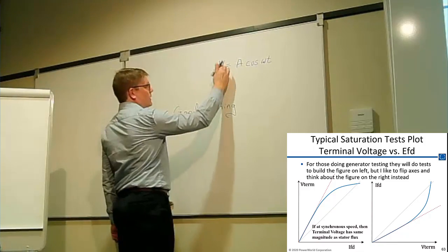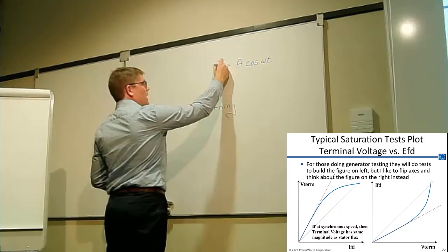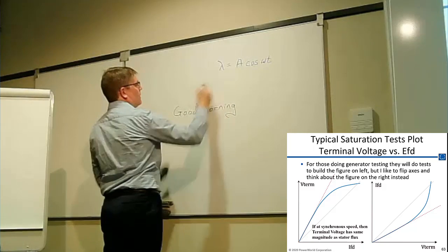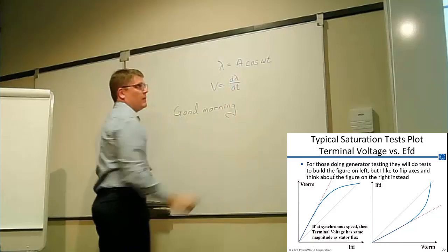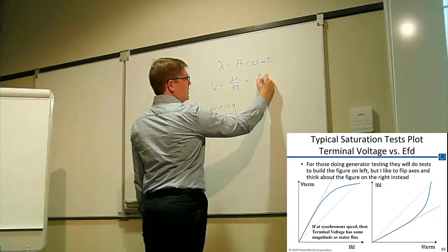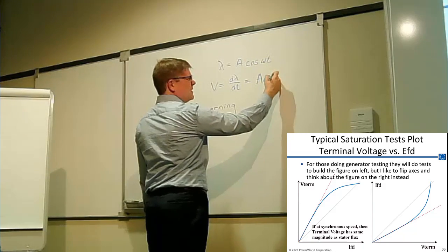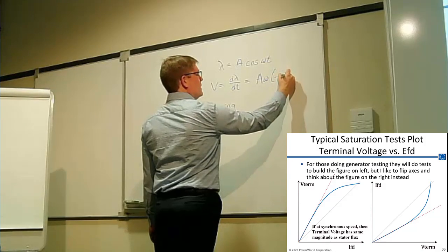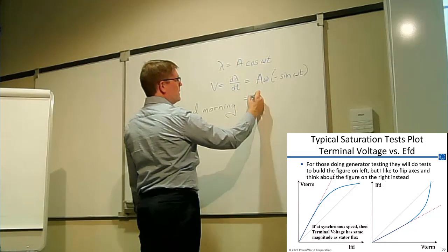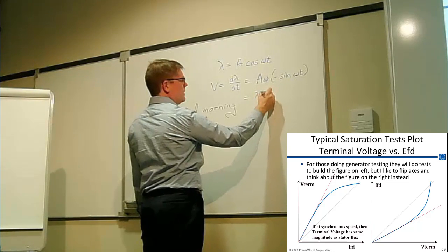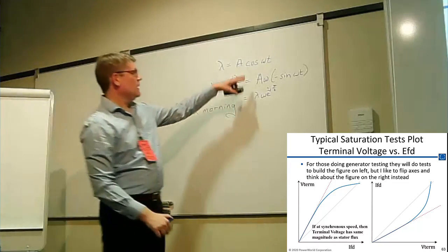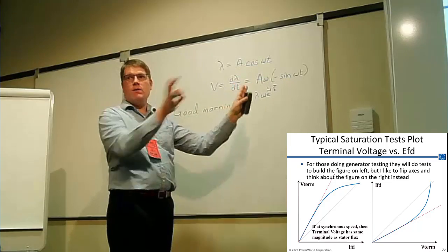that flux. You remember we're talking about voltage, the derivative of, sorry, not voltage. Voltage is the derivative of flux with respect to time. And we're going to be talking about phasors and things at 60 hertz. So the derivative of this is just A omega. Derivative of cosine is minus sine. Is that right? So voltage is, you could think of it as flux times omega e to the j pi over 2. I can't remember if it's plus or minus in there. But the point is, all you're doing is taking the flux. If you take cosine and sine, they're just 90 degrees out of phase with each other. And the magnitude increased by omega.